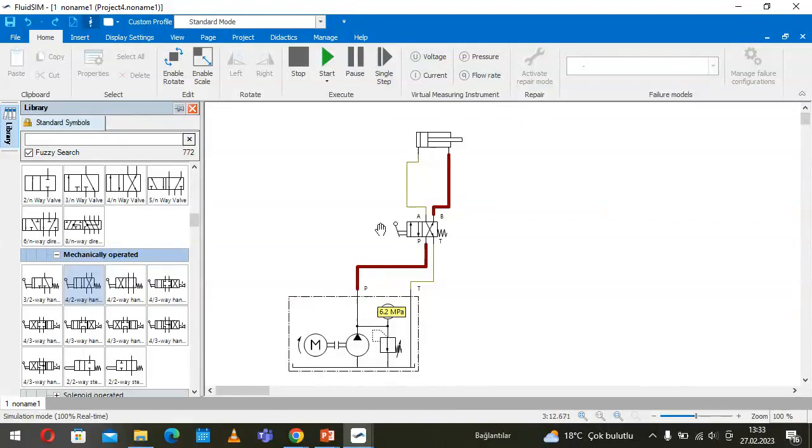If you want to keep the piston somewhere in between, we cannot realize that with this 4-way valve, because it has 2 positions: one of them is responsible for driving the cylinder forward, and the other one for driving it back to its initial position.